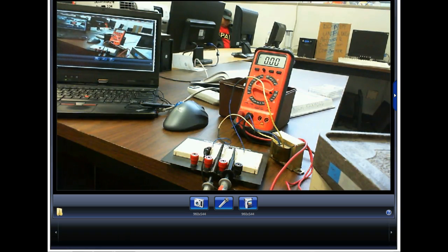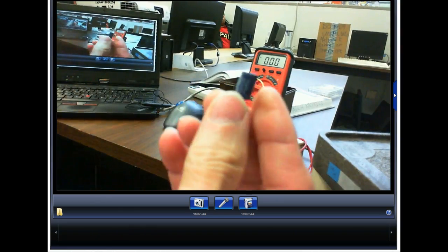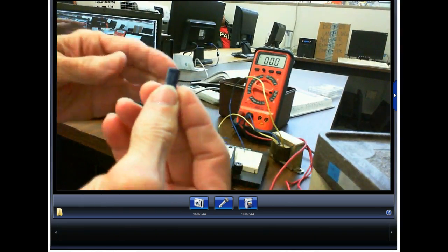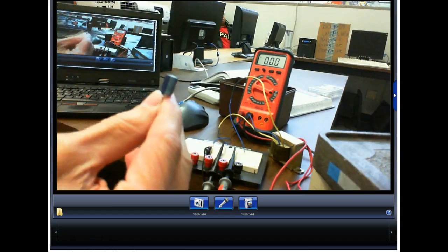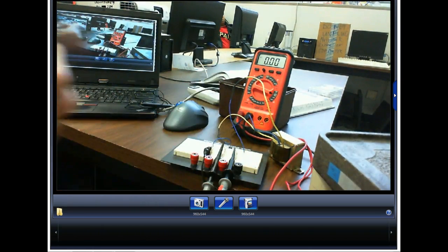So there we go, guys. Now we're going to show y'all something. This is what we're working on. So right now we got the first part. This is probably one of the most popular devices used to filter because it's very cheap. We got 2 types of filters we'll use. In switching power supplies, they use inductors, and we'll talk about that. In linear power supplies, we use capacitors. And why do we use capacitors? Because they're very cheap. They do the job for us cheap. Inductors use copper. You use copper wire, and copper's not cheap, right?